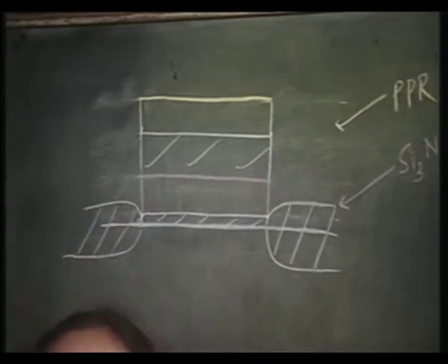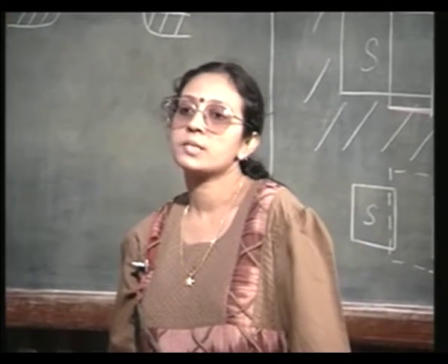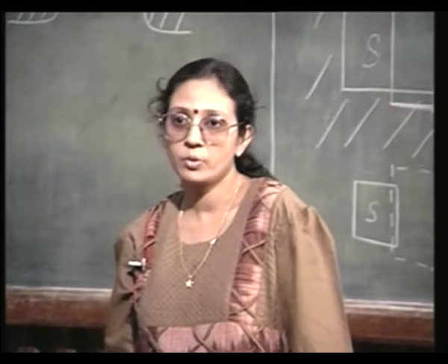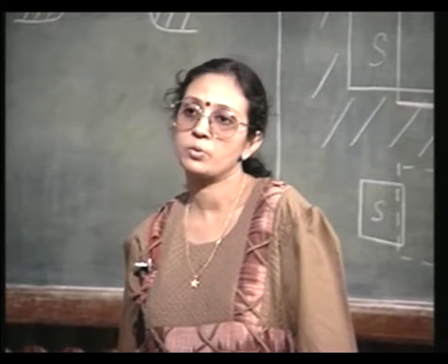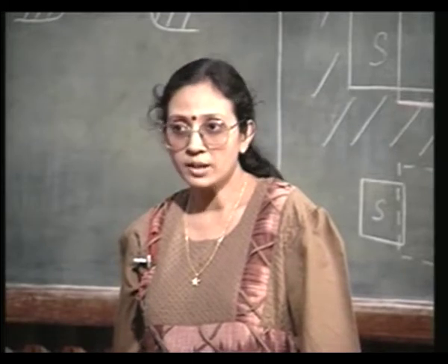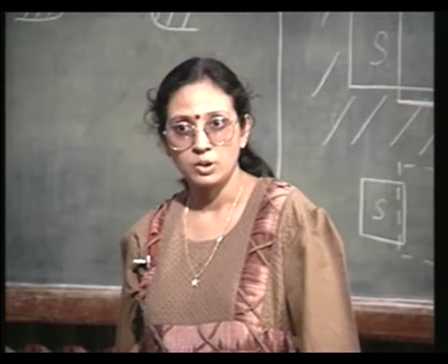So, even if you have a very thick field oxide, you are losing surface planarity only by half the amount. That is, even when I want to grow say 10,000 angstrom, even if I want to grow say 1 micron thick field oxide, on the surface only 5,500 will project out. Okay.